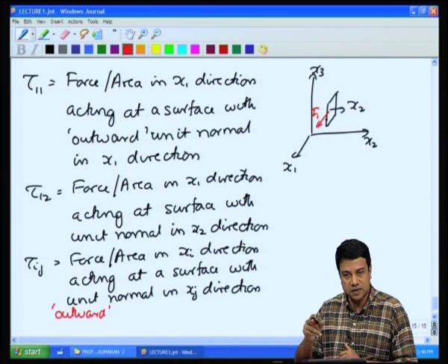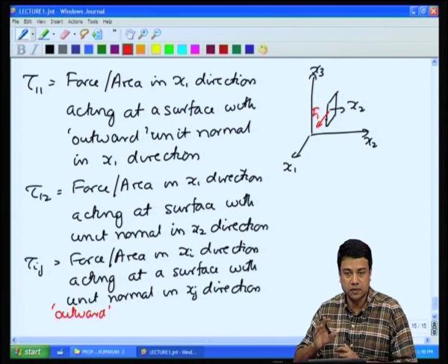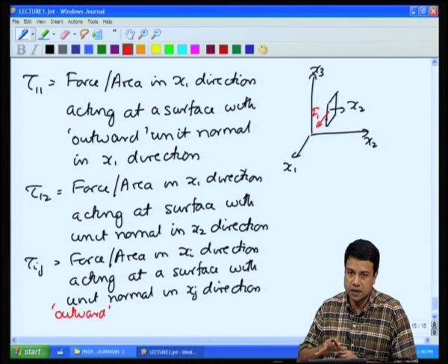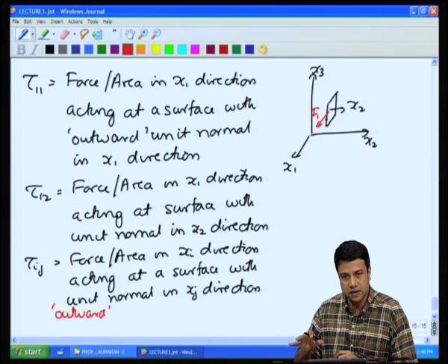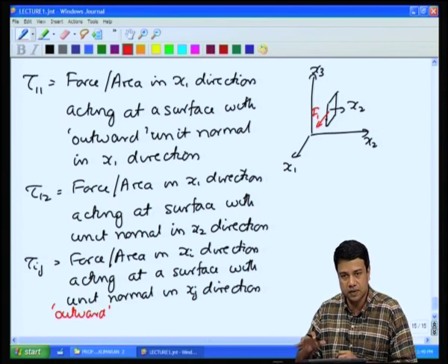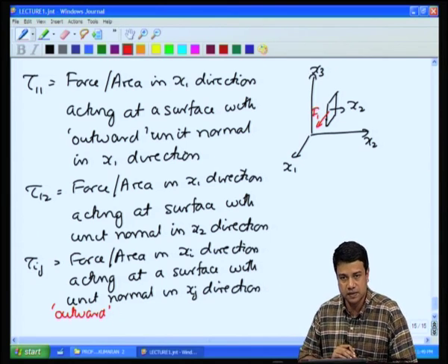So, I have to have constitutive relations for 9 of those components separately, okay, if I wanted to write equations in component form. Whereas, the way that we do it here, we will treat the velocity itself as a vector object, the flux itself as a tensor object, and derive relations between the flux and the velocity, write down conservation equation, constitutive relations for these.